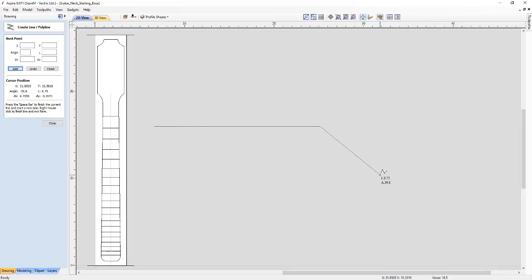Then all we need to do is create the actual angled part of our profile. This is also very simple, so we can actually snap to the increments of whatever is set in our snapping options. If we press F4 when we're not in a tool, we'll be able to adjust those. Or we can still use those keyboard shortcuts. So I'm going to type in 15 and the letter A. You'll see down the bottom right hand corner that will say A:15, which means the software is ready to take a length now at a 15-degree angle. And I'm just going to type in 9 inches there and press enter like so.